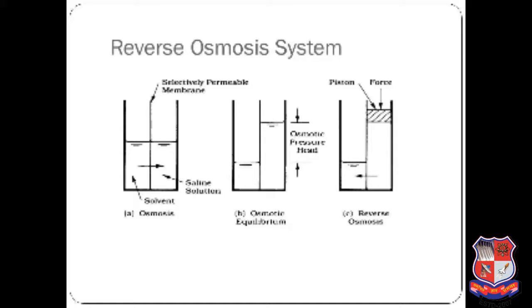About half of the molecules are at any one time in such clusters. When pressure is applied to the membrane, molecules on the high pressure side are incorporated into the ice-like structure, replacing molecules which melt away on the other side. Ions in water, surrounded as they are by water molecules aligned to shield the ionic charge, cannot be made to fit into the ice-like matrix.